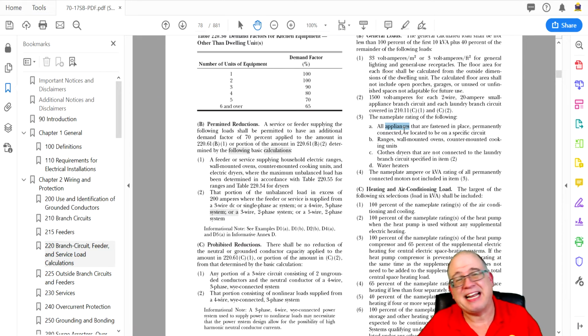The only other thing that I can tell you that's different in here is that we're not applying 25% of the largest motor. We're not doing that for the optional method. Okay? So you don't have to worry about that mess as well. All right? But I just want you to be aware of all these things here. Don't make it complicated. If it's there in your question, apply it. If it's not, don't apply it. All right? Okay. Let's move on now to the presentation.